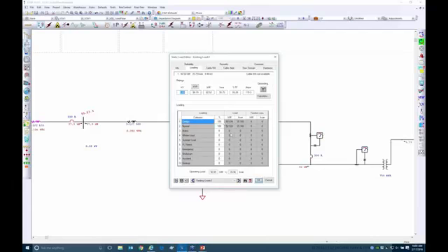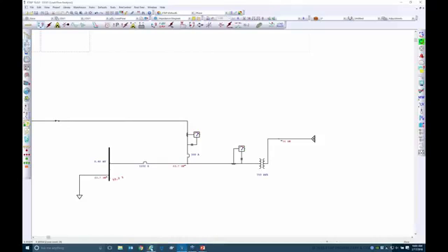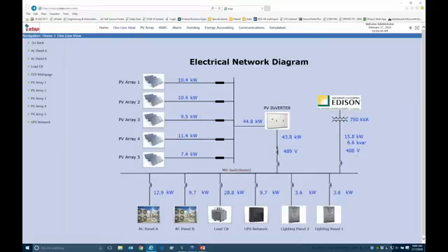The load was actually about 64 kilowatts or so in the system. So I should have been selling about 34, but that's really not what's happening in my system. What I'm actually doing is buying 15. So there's a definite difference between the design model and the planning model. And by actually having them in ETAP itself, you can now start tuning the model to make sure that what you get from your simulation and what you're seeing from the real system actually corresponds and jives together.